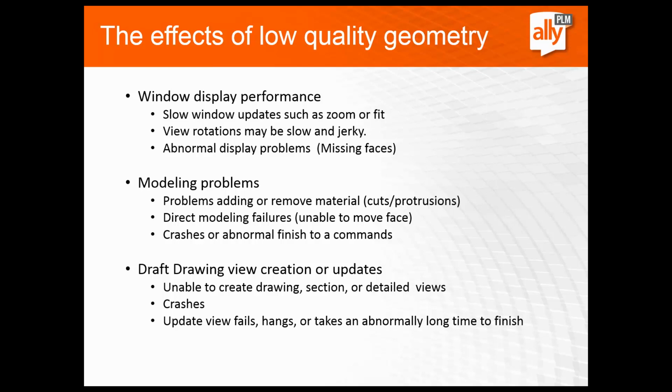When you take your model into the draft environment and you're trying to create drawing views, you may not be able to create those drawing views. Again, you may run into some crashing issues. When you're updating your views, sometimes that fails or hangs up or takes a really long time to finish. So a lot of adverse effects here from low quality geometry.